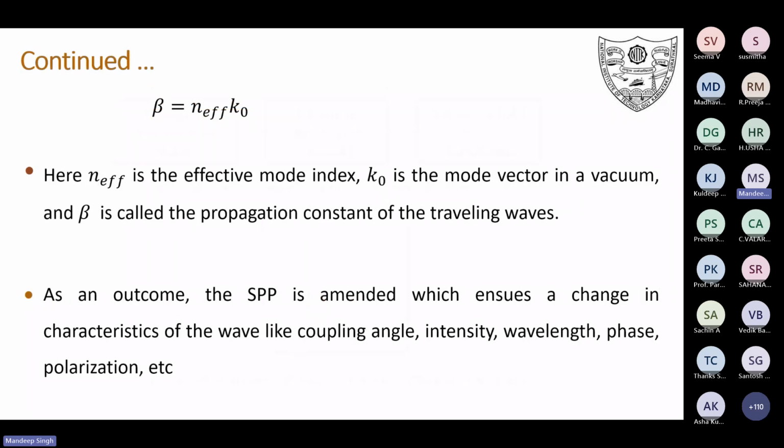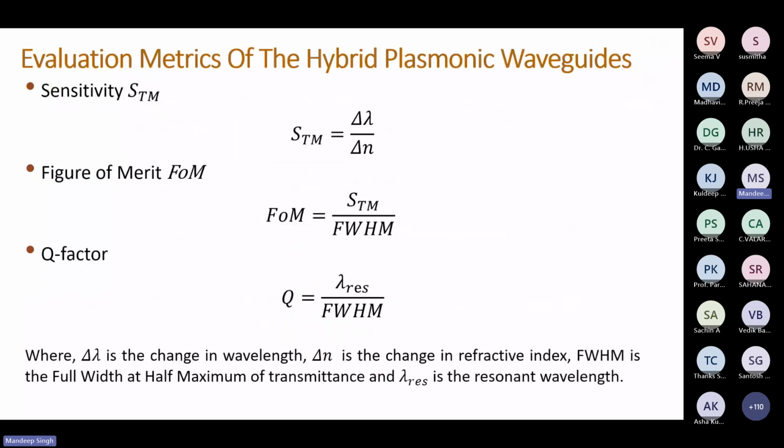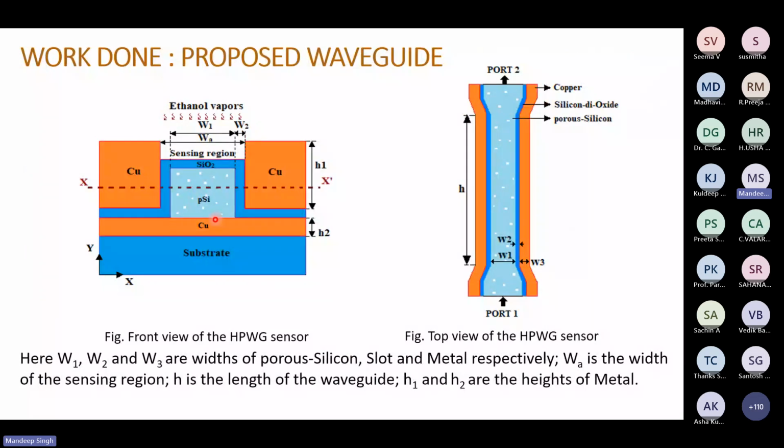First I will show you the design, and then we will discuss the starting point. For CMOS compatibility, we need CMOS compatible materials. You can see here we are using copper, which is CMOS compatible. Moreover, there is a substrate, and then we have to deposit the copper. Now instead of using porous silicon on the top, we have used porous silicon deposition over the copper and then covered it with the dielectric. So we have modified the design and then covered it with the copper.